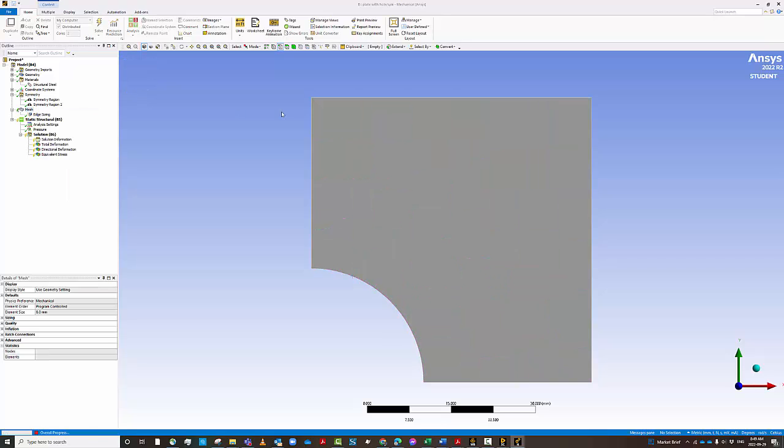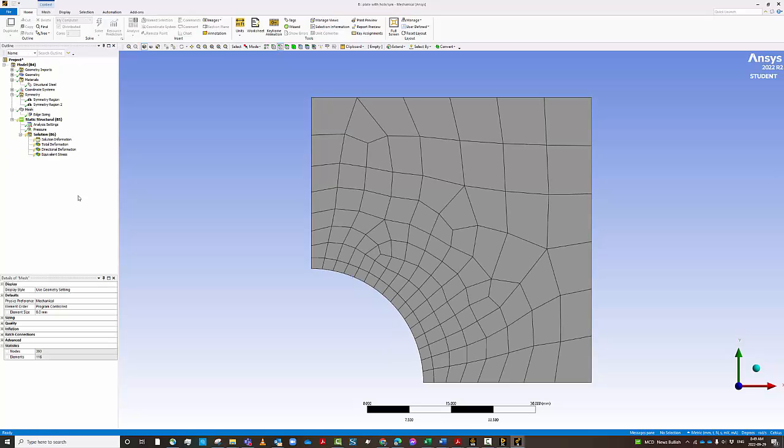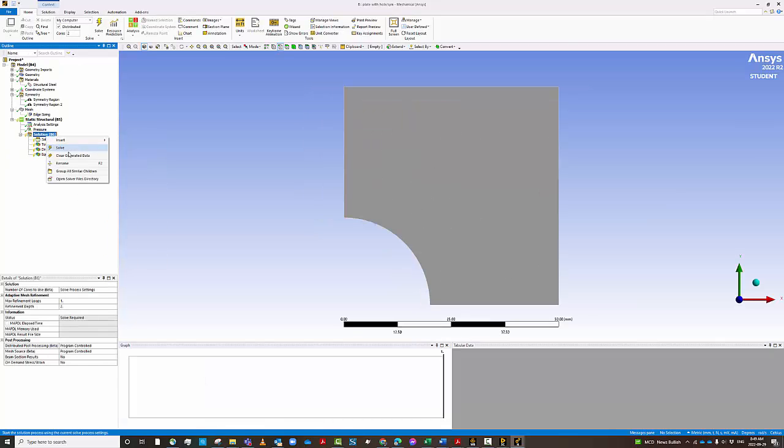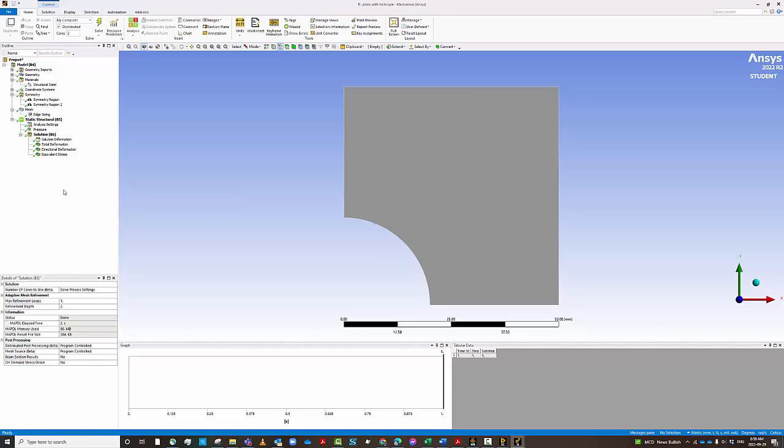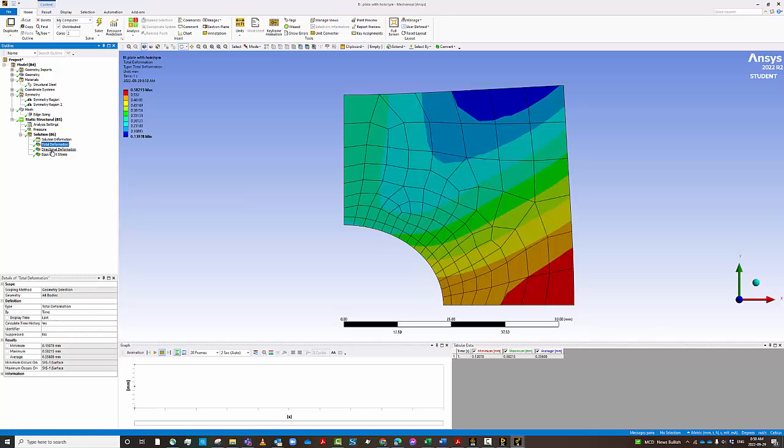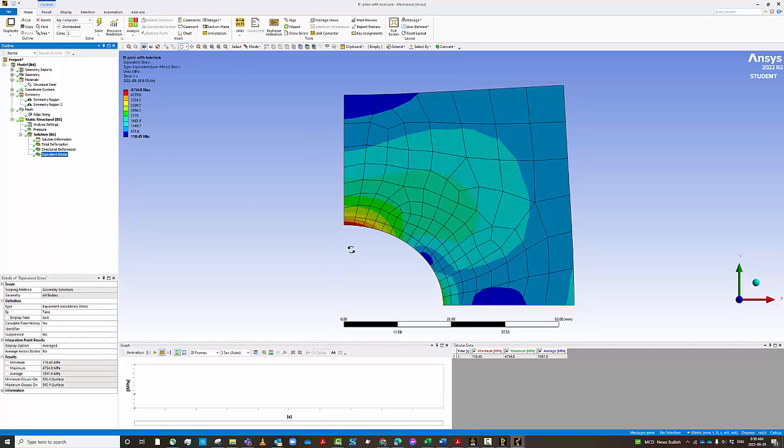And once you update your mesh, of course, we didn't face the rigid body motion, remember? That's one thing. So this is one of the advantages of using symmetry. You already constrain the solution much better. You don't need to add the rigid body motion. So the solution is done. So you can see here the deformation. The mesh is much better, directional, and so on.